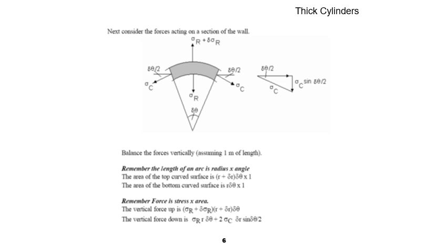Okay. But what we are interested in is equilibrium of forces, right? So when we take equilibrium of forces, sigma C, they have a very small angle, depending on whatever subtended angle that we take. Now let's say we take del theta. Therefore, the angle for each side will be del theta over 2, right? So if we take out, we have sigma C,